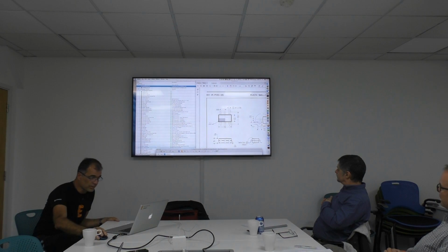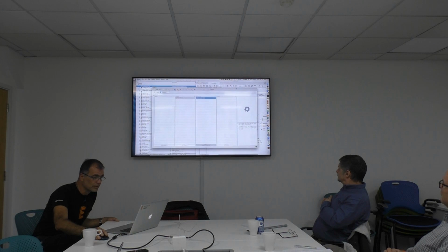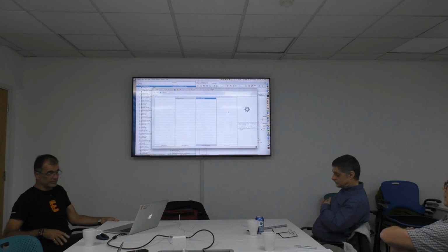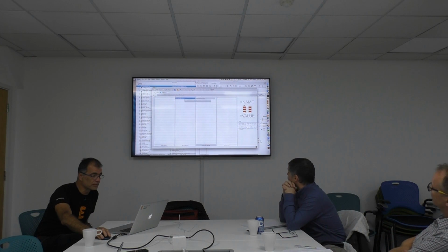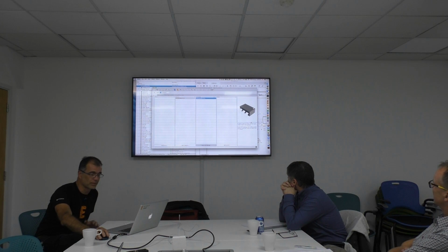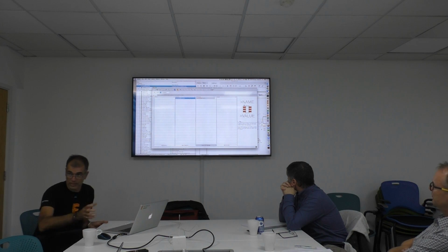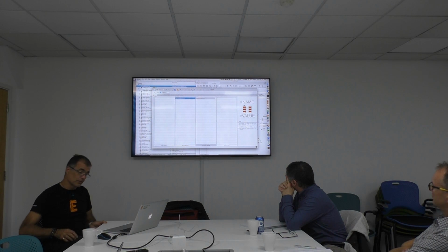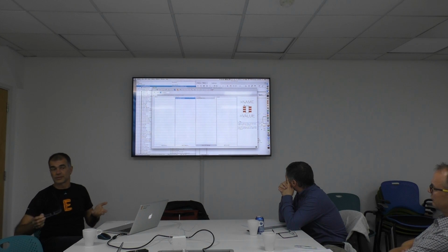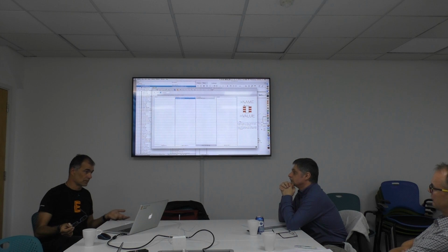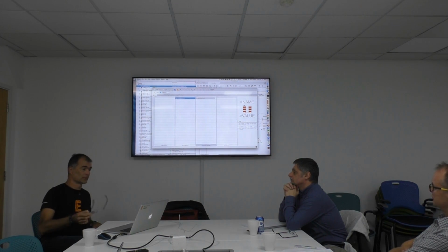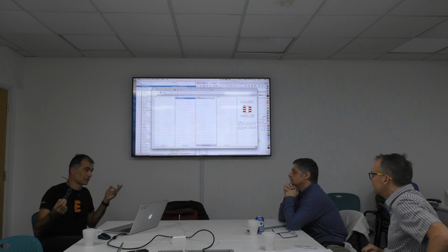And if I move the library window up here, you see I have my footprint. I don't have a preview yet. This will be done. The priority is not so high there, but now we have it. Yes, these two now fit together. Easiest way to have both. But of course, you can't use this for packages like connectors and so on. That's something you might really have to draw in the footprint.